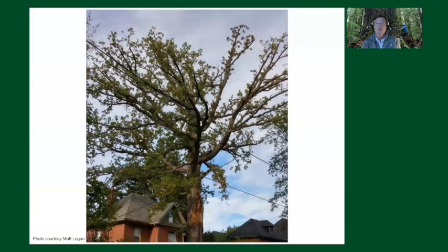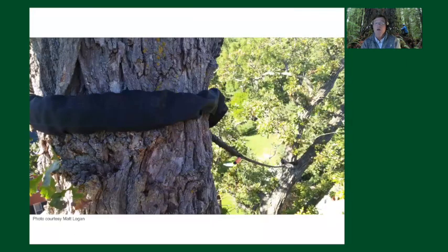And this is what the tree looked like after the assessment. And the only other thing that was done, you may be able to see if you see my cursor, was this other large limb attached low and over the house. As an extra precaution, we installed an 8-ton Cobra cable, in the unfortunate circumstance that the branch decided to give way. It would be covered. So we went through a variety of techniques here and some mitigation strategies and how they were applied.